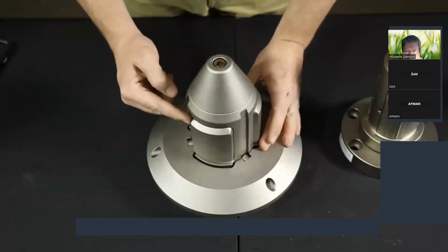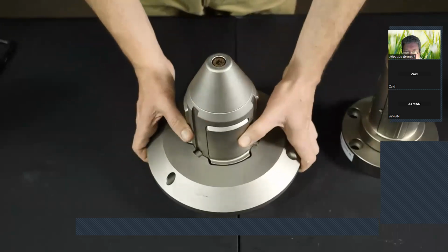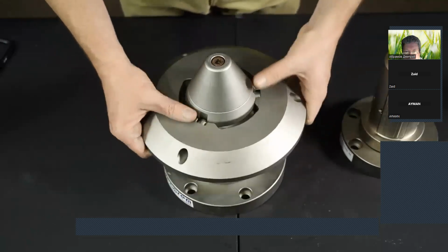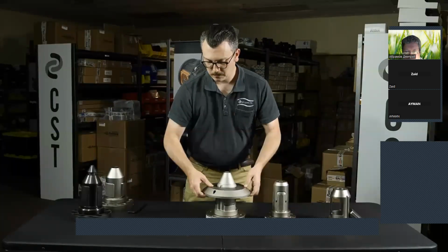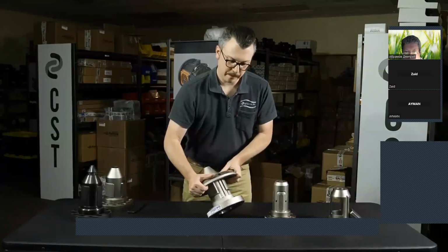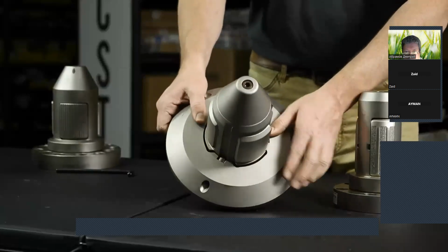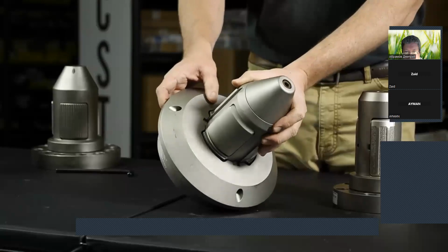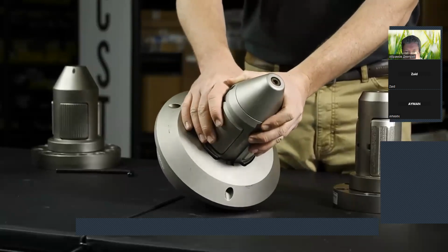Our core ejector plate is made from aluminum with a nickel coating, rather than steel. This means it's lighter. Why is that? It builds up less inertia, so while it still easily pushes off the heaviest rolls, it doesn't build up as much force and become a safety risk if the roll stand ejector arm gets stuck or malfunctions, which can be a problem with some OEM ejector arms.